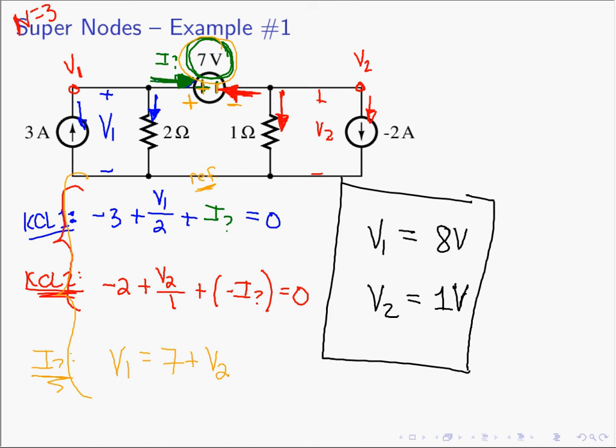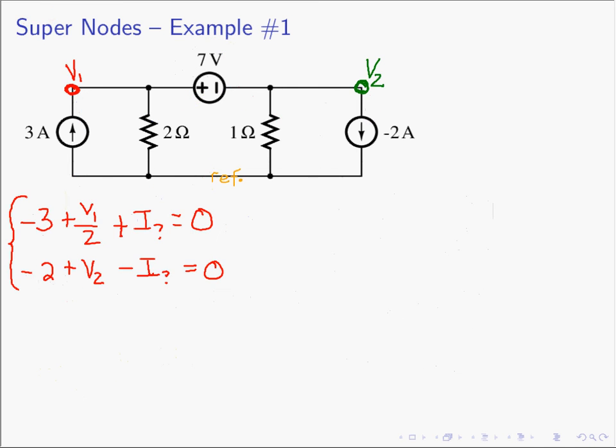So we see when we have voltage sources in our nodal analysis, we can't find the current. Remember, nodal analysis is a systematic algorithm for applying KCL, and we can't find the current in a voltage source, so voltage sources give us a bit of trouble. This is how you solve it, and that works, but let me show you kind of a shortcut method, if you will, just a different view.